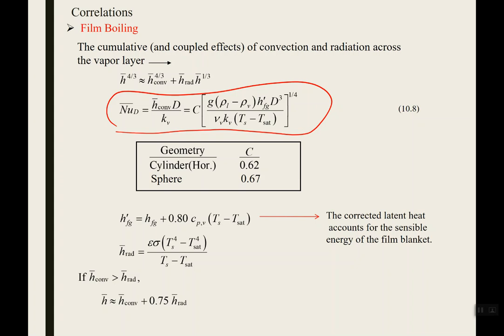So we may just assume that our H is really, really high relative to the other thermal resistances that we're caring about, and so we could neglect that thermal resistance on the boiling side and just figure out what's happening in the rest of our system. That would basically be making the assumption that the boiling fluid is just mixing really well, so it's carrying away heat from the surface extremely quickly.